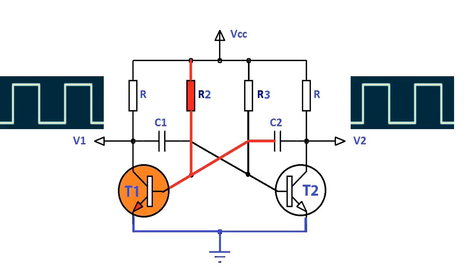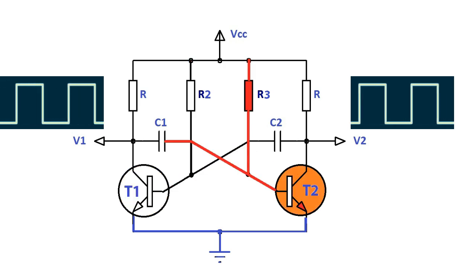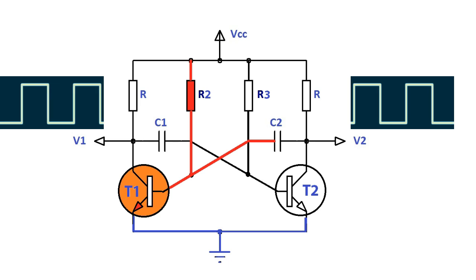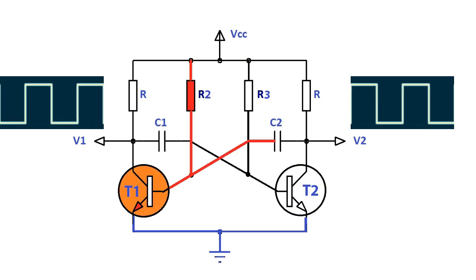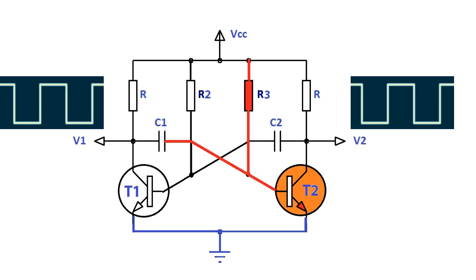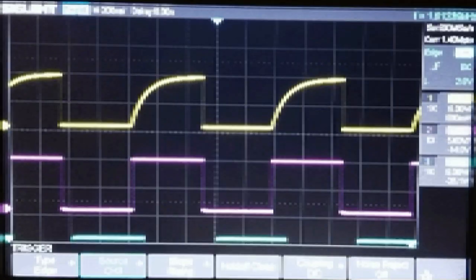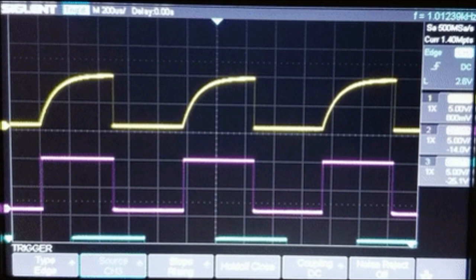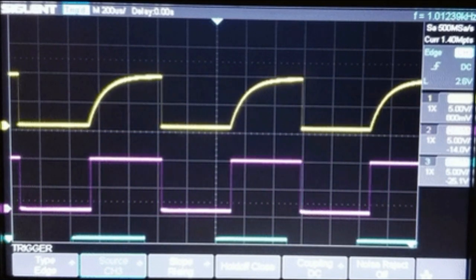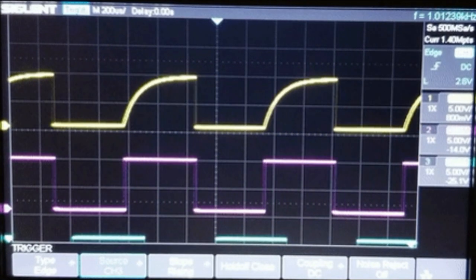The amplitude of the output waveform is approximately the same as the supply voltage, VCC, with the time period of each switching state determined by the time constant of the RC networks connected across the base terminals of the transistors. As the transistors are switching both on and off, the output at either collector will be a square wave with slightly rounded corners because of the current which charges the capacitors. This could be corrected by using more components, as we will discuss later.